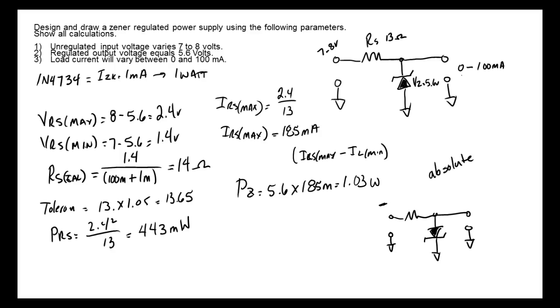1N4734. Now the only thing that I don't specify, remember, the 1N4734 has a tolerance. And what's the tolerance? Y'all remember? So here, what y'all should have probably said is the 1N4734A. Yeah, so the A is a 5%, and if you don't put it, it's what? It's a 10%, right? You understand? Sometimes it's not critical. So I think all the ones that we have are A's, I think.